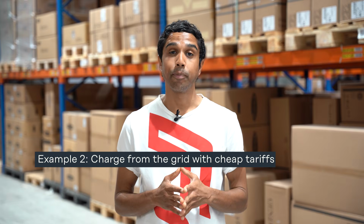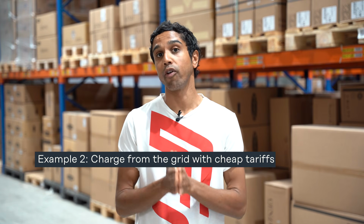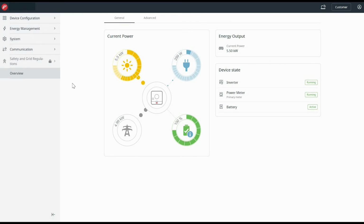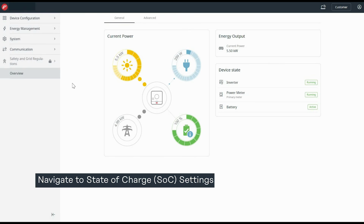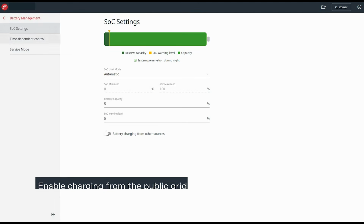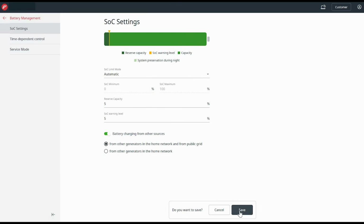In this second example, we're going to enable charging from the grid when you have access to cheap or free electricity during the middle part of the day. For this function, we want to allow charging from the grid, so we need to navigate to the state of charge settings, which are located in Energy Management, then Battery Management, then SOC settings. Tick Battery Charging from other sources and select the option that includes charging from the public grid. Then click Save to apply the settings.